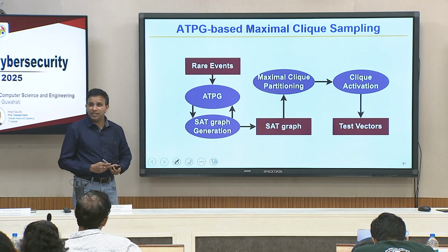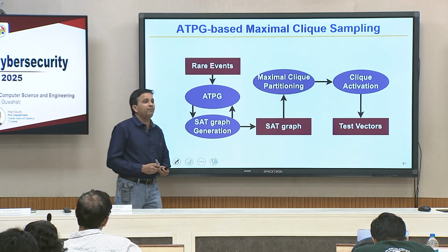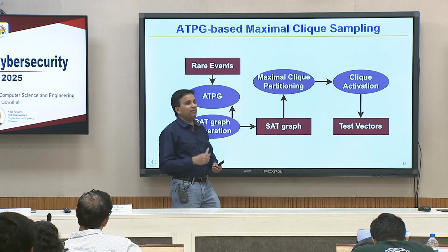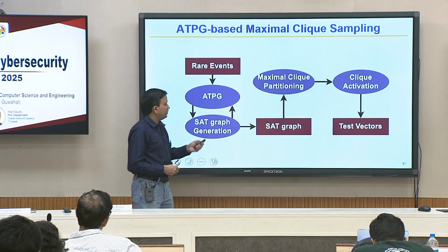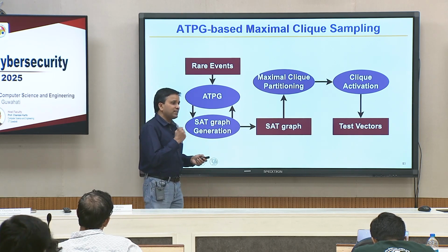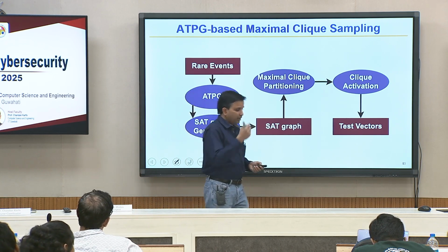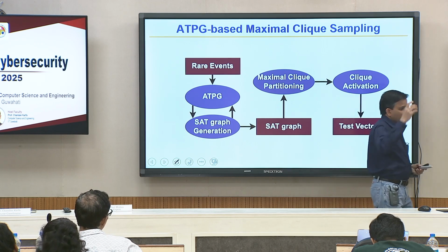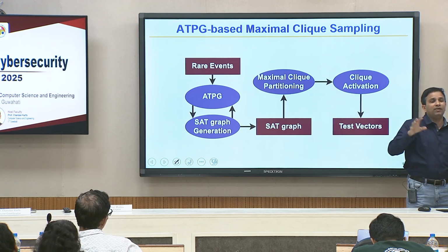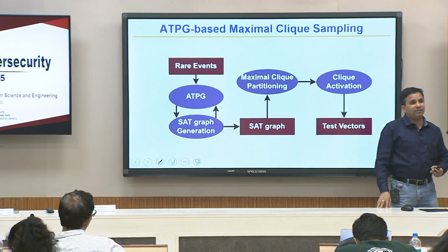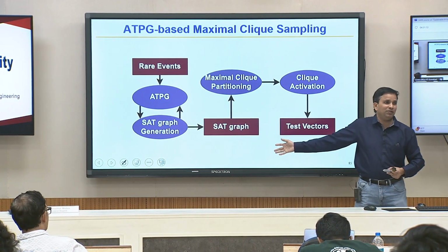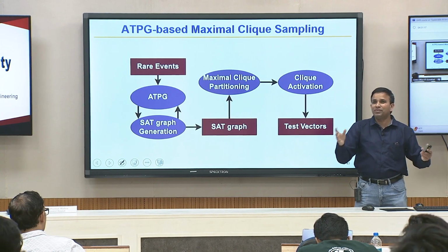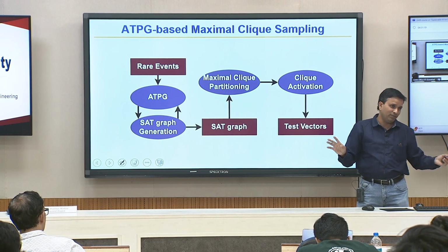ATPG has its own idiosyncrasies, but it is significantly faster, and specifically the commercial ATPG tool is significantly faster than SAT solvers in solving the problem. And another thing you have to understand, Synopsys adopted this solution for laser fault injection, all of them, because we were actually running on their million line designs, since their ATPG tool will run on million line designs. But if you convert into CNF and try to give it to a SAT solver, you can forget about it.